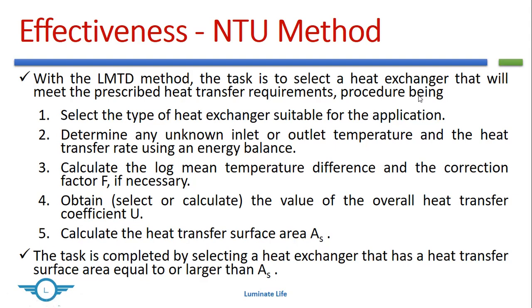requirements. So a generic procedure was, first we will select the type of heat exchanger, whether it is a parallel flow or a counter flow or a cross flow arrangement. Then from the given data, by using an energy balance, we will try to find out all the temperatures, all the inlet temperatures as well as the outlet temperatures.